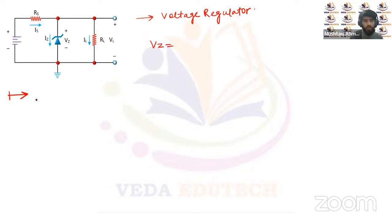IS is the source current, IZ is the current flowing through the Zener diode, and IL is the current flowing through the load resistor. But we know that the Zener here is a voltage regulator. Whatever the voltage across the Zener, the same will be the voltage across the load resistor. So VZ has to be equal to IL into RL, which we can call VL.